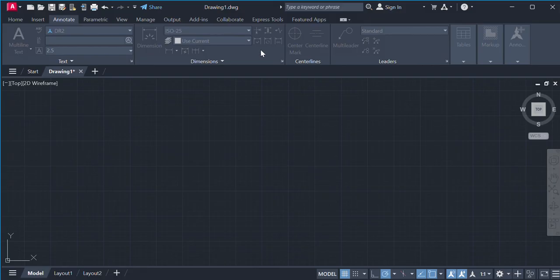The next, we're going to the primary unit. You want to make sure that you keep your unit format at decimal and your precision at 0, because you don't want 14.2, 14.35. You want to keep everything at a whole number. And decimal separator, that's our standard. We have a comma, and because our precision is 0, it will round off to the nearest whole number. All right, then just check that everything is going well, and then you can say okay.